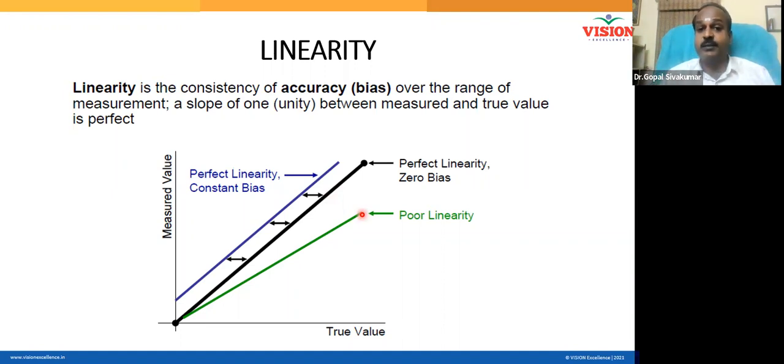Now action taking will be very difficult for you. Am I correct? Correcting error is difficult for you. So nonlinearity is an unpreferred scenario. When your readings are coming like this, the choice of the gauge you have taken is not appropriate. Please try to break the range.